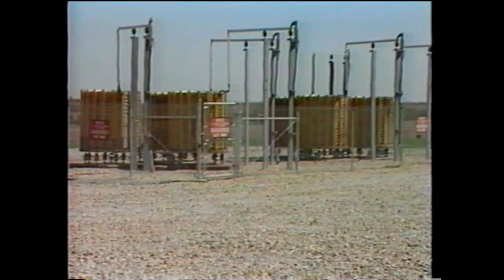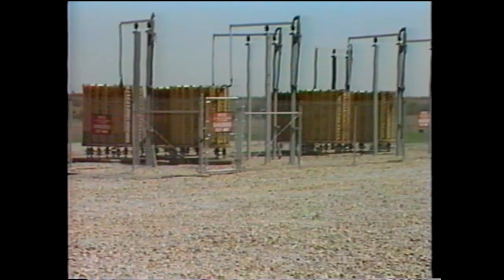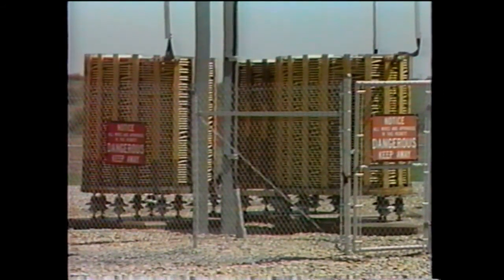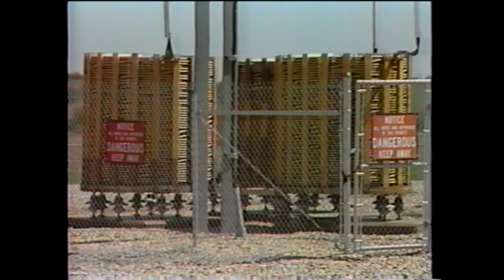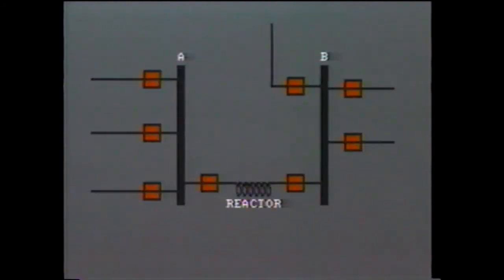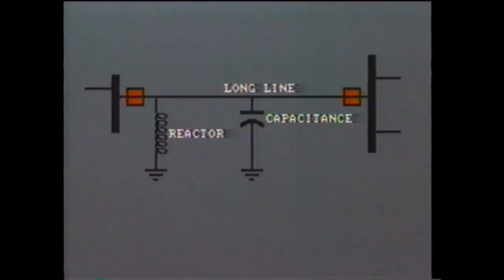Now at this point, let's extend our overall view of transformer protection to include reactors. This is because there are many similarities in construction, and therefore protection is also similar. Generally, reactors are air-cooled or oil-immersed single or three-phase windings on an iron core. Where is the reactor installed? Well, typically in a grounded neutral to limit fault current, between buses to reduce magnitude of current flow, or shunt-connected between line and ground to compensate for capacitance on long lines and prevent high voltage levels.